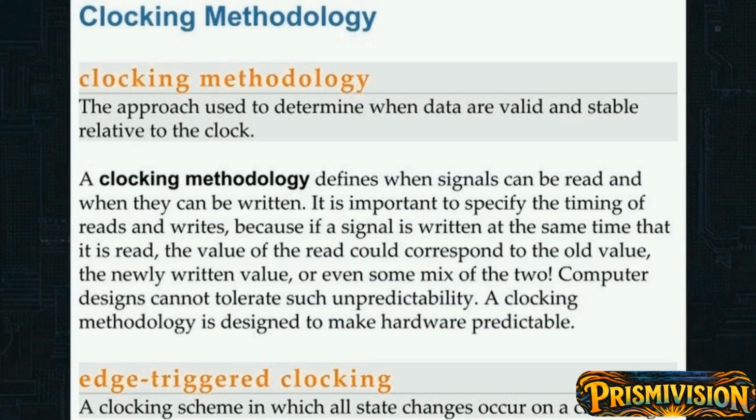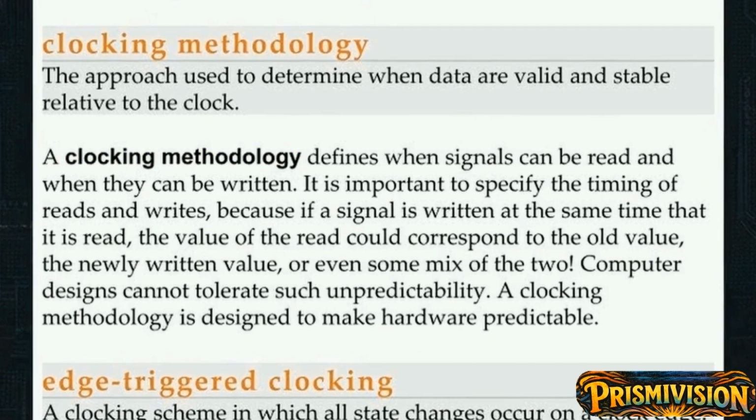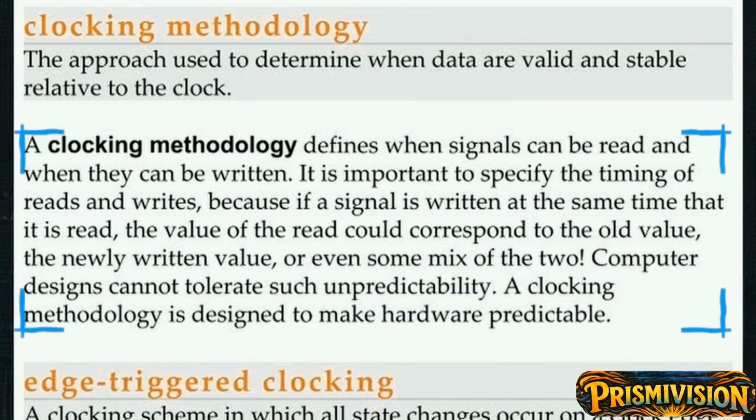That conductor is the clocking methodology. This set of rules defines exactly when state elements read incoming signals and write them out. It prevents a specific failure. If written at the exact same time it is read, the resulting value could be an unpredictable mix.